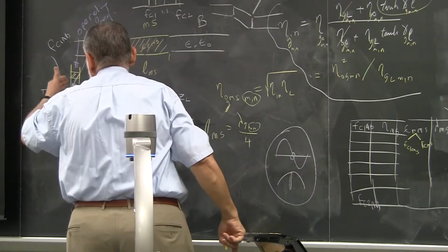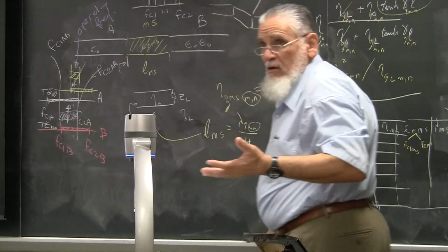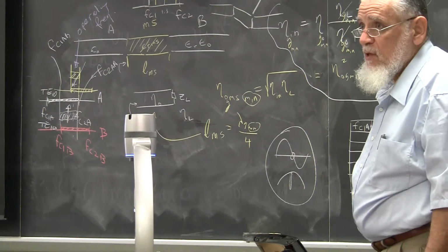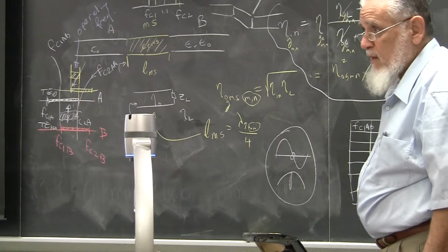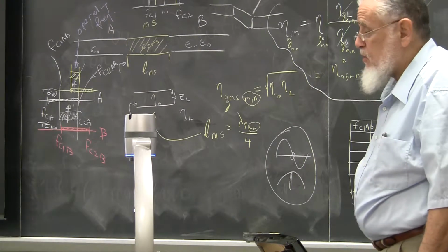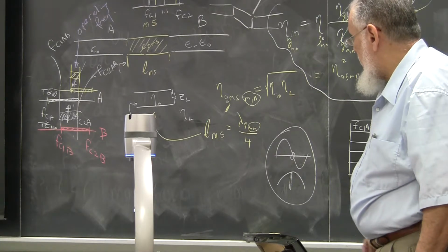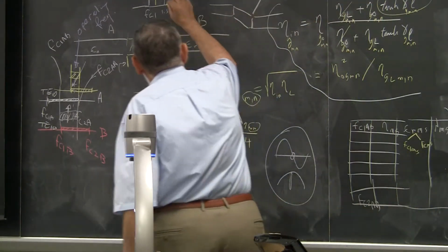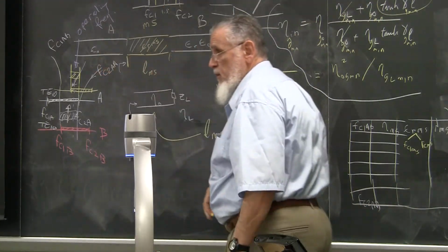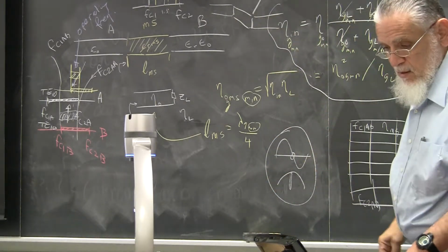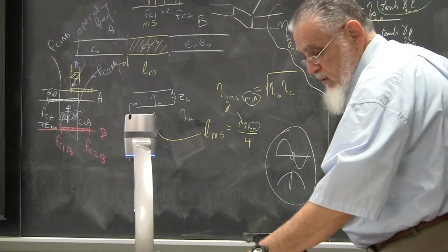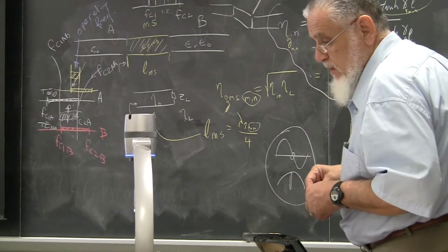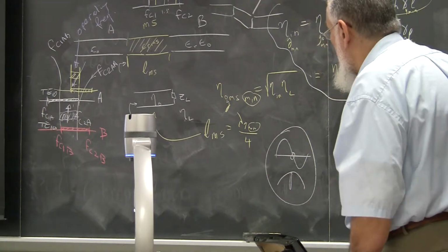So working with the middle frequency is, call it the first iteration. Designers obviously try to offset things to use the lower attenuation band or the lower attenuation frequency range of the guide, right? You don't want to really be in the middle. You want to be a little bit to the right. So your center frequency typically moves to the right a little bit. So keep all that in mind when you design. I know we don't have equations or attenuation information to work with, but like I said, just be aware of all that.